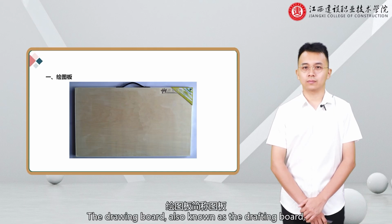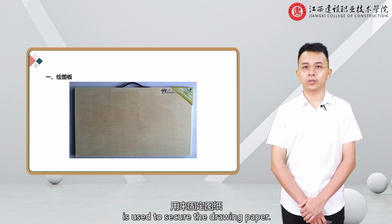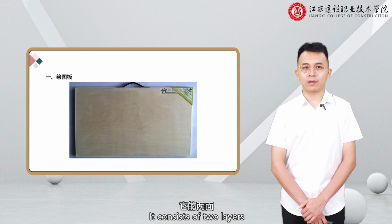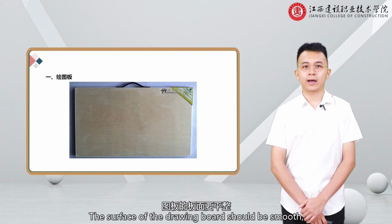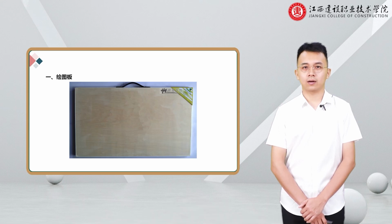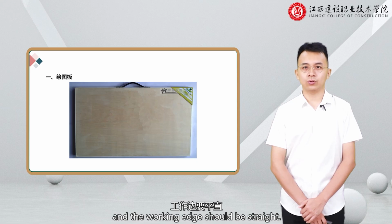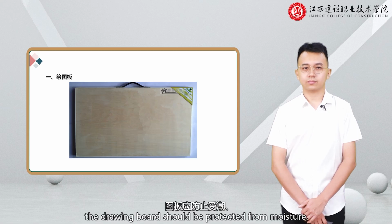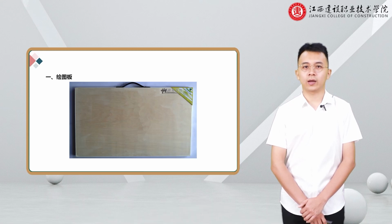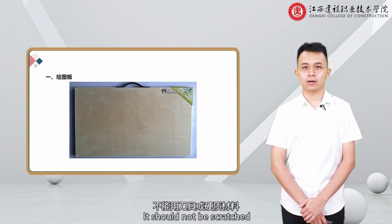The drawing board, also known as the drafting board, is used to secure the drawing paper. It consists of two layers of plywood with hardwood strips along the edges. The surface of the drawing board should be smooth, and the working edge should be straight to prevent warping and deformation. The drawing board should be protected from moisture, direct sunlight, and heat. It should not be scratched with knives or hard materials.